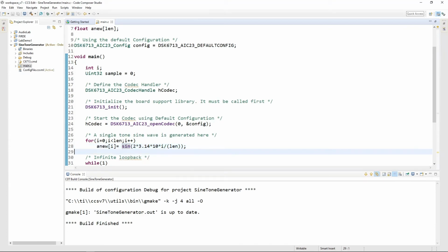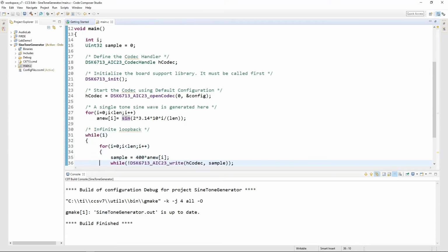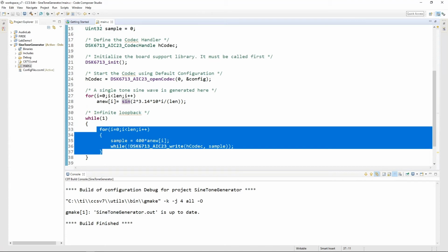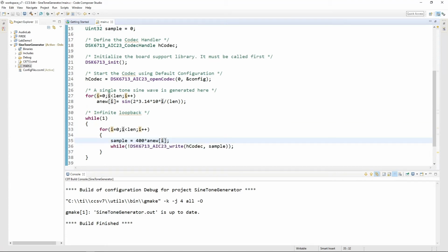This can be easily managed by the use of an infinite loop. Here we have used a while(1). In the while(1), I have tried to read the 2000 samples of sine one by one. In the first iteration, the 0th sample will be read, which has been multiplied with a gain. This is now the current sample. This sample will be output using the write command.